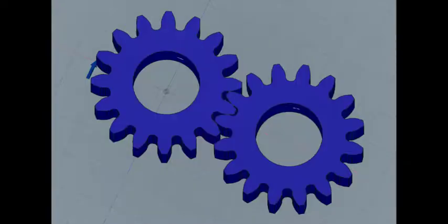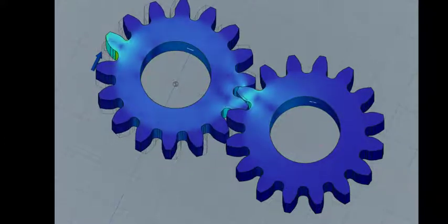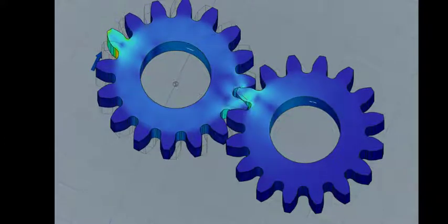We can also animate this to give you a notion of how the gears rotate and deform under the application of the applied load. This shows the large bending stress in the tooth loaded at the tip, but also shows the contacting stresses and bending that are associated with the teeth that are in the meshed region. I've used an exaggerated deformation so it's much easier for you to see.